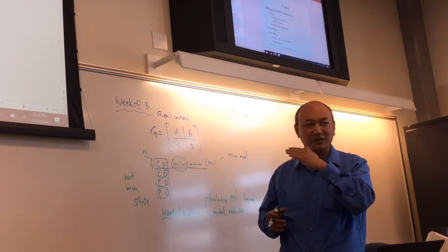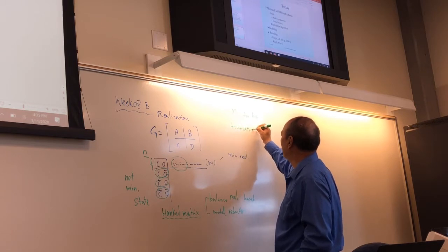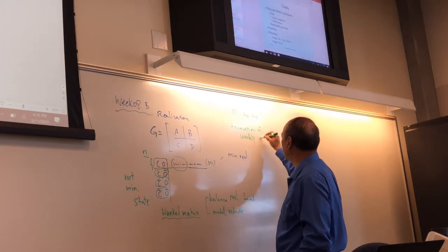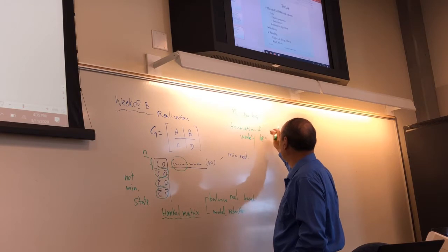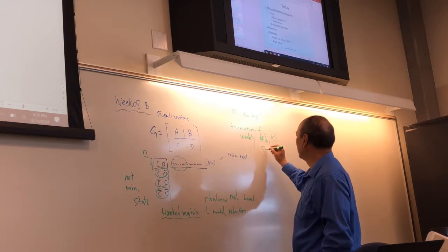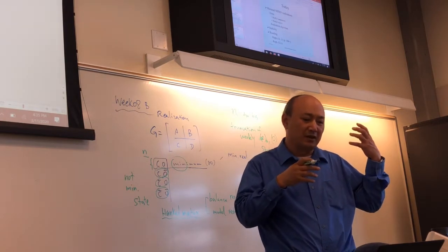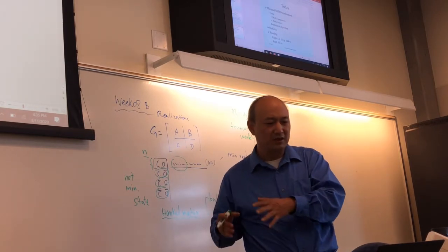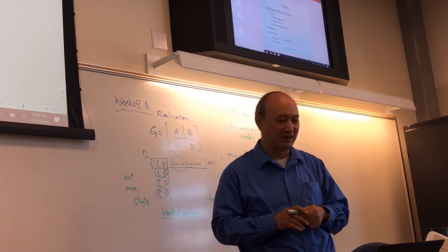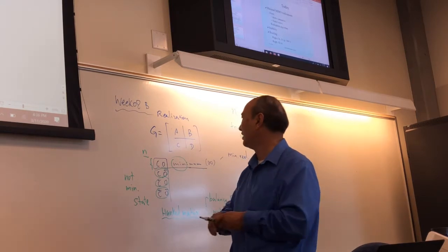So can I do some truncation of weakly controllable and weakly observable states, truncation of the states. That is the idea of model reduction. That means I ignore those weak states. Okay? I keep those more important states. Then the system is still a good representation of the reality.